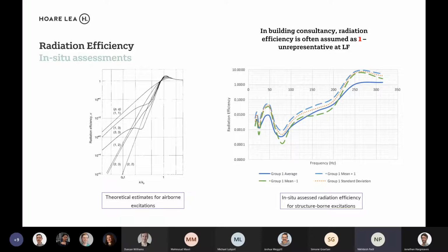we found that obviously it's not as representative at low frequencies, because it's less than 1 at low frequencies, which could mean that you might over-predict and impose tremendous requirements on any isolation or structure that you are designing. So that's something that we're also looking at, but it's interesting to see that whether it's a structure-borne or airborne excitation, the general curve remains the same.